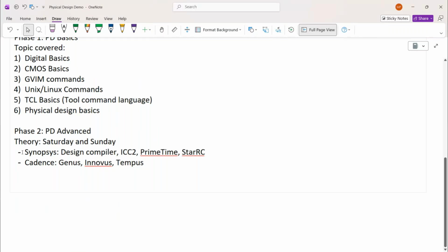In Synopsys, the project is ORCA top, with around 52K cells and 40 macros, and we do full PnR on that big netlist. In Cadence also, we are using a netlist having 64K cells and 42 macros.